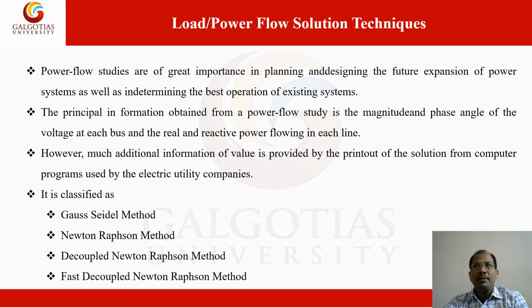In our syllabus, advanced power system analysis, we are going to discuss first the Newton-Raphson method, then the decoupled method, then the fast decoupled method. First, we are going to discuss Newton-Raphson. Gauss-Seidel is the UG level course syllabus, so we are not going to discuss the Gauss-Seidel method. We are going to directly start with the Newton-Raphson method. Then there are certain assumptions we have to apply on the Newton-Raphson load flow analysis. Then we get the decoupled Newton-Raphson method. Then further we apply certain assumptions, and we can say that it is the fast decoupled method.